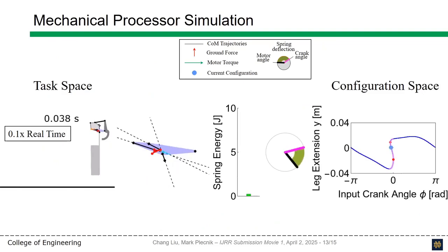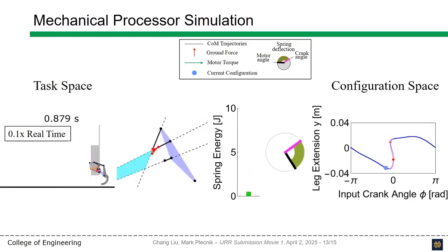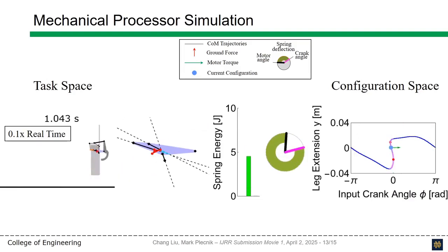The cycle is further illustrated by dynamic simulation. The thick green arc is a visualization of series elastic spring deflection, and the magnitude of the motor torque and vertical ground reactions are visualized as generalized force vectors pushing on the mechanism in constrained configuration space. In real time, the mechanism's motion is essentially invisible.